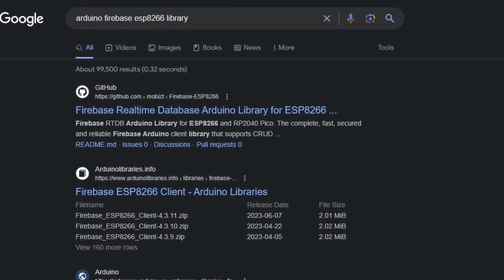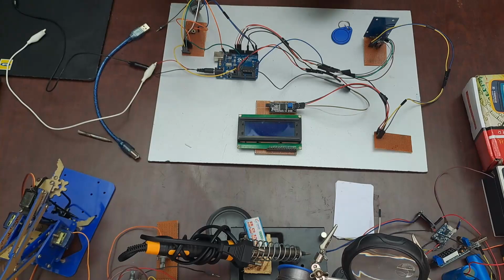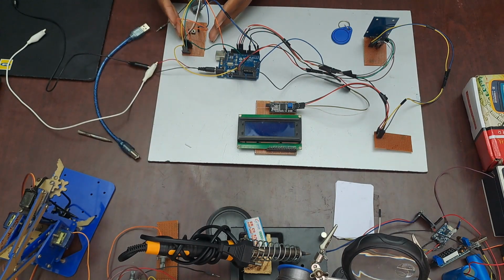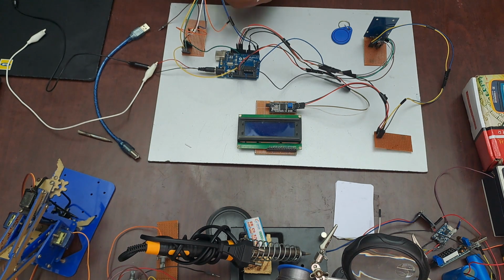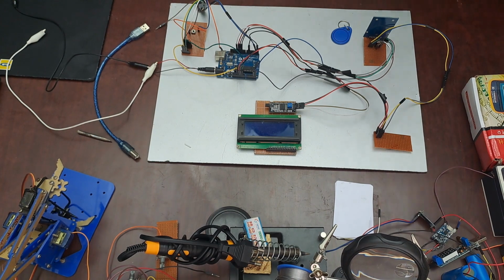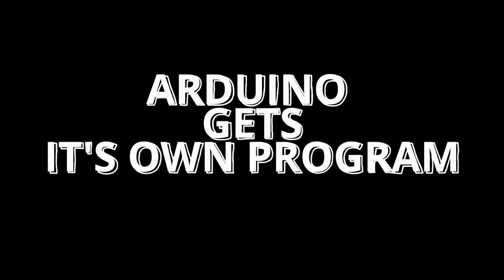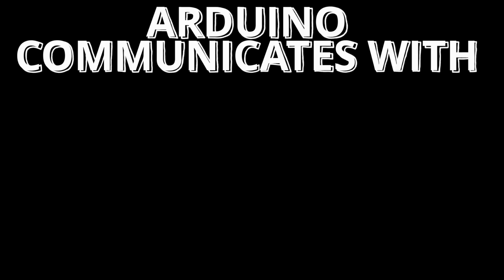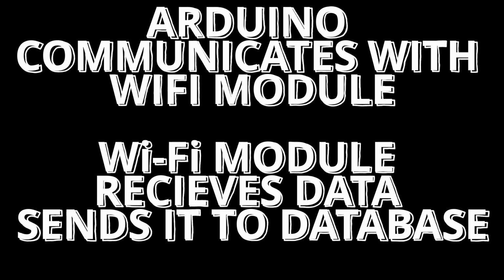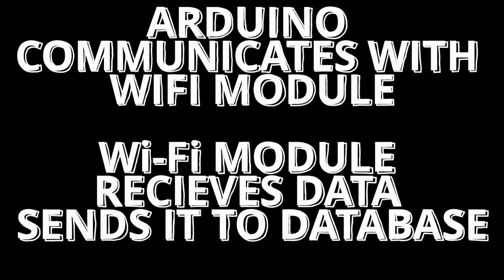So understand that your Wi-Fi module is like a separate microcontroller from your Arduino. So you use your Arduino to program your Wi-Fi module, then you program your Arduino and enable it to send data through the serial communication to the Wi-Fi module. So Arduino programs Wi-Fi module. Arduino gets its own program that allows it to communicate and send data through the serial communication to the Wi-Fi module. The Wi-Fi module then receives that data and, as per the codes, sends the received data to the database.